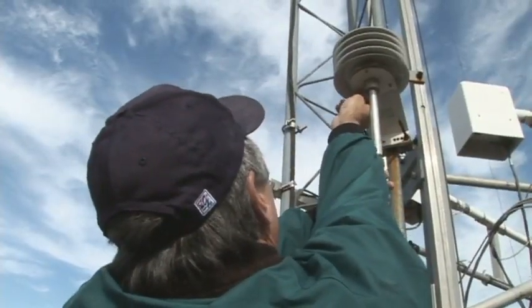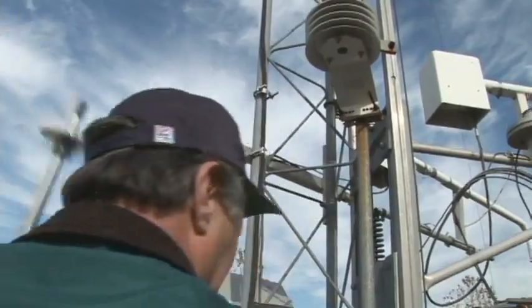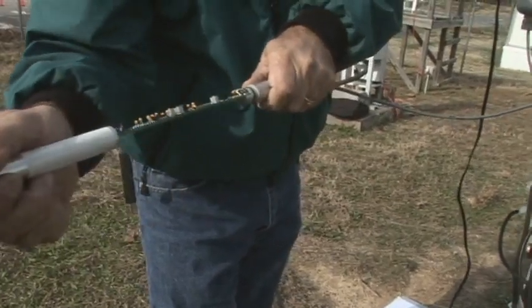The relative humidity probe is removed from the housing. Care should be taken so that the probe is not damaged. The same issue exists with this probe as with the temperature probe. Insects can nest in these housings. Caution should be taken. Once the probe is removed, insert the probe into the calibration solution.